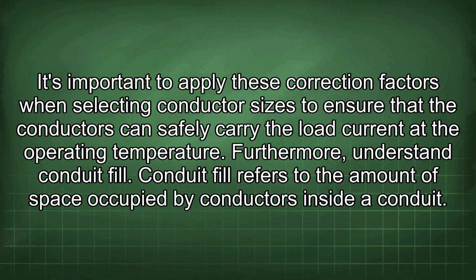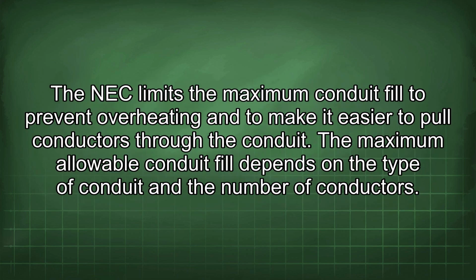It's important to apply these correction factors when selecting conductor sizes to ensure that the conductors can safely carry the load current at the operating temperature. Furthermore, understand conduit fill. Conduit fill refers to the amount of space occupied by conductors inside a conduit. The NEC limits the maximum conduit fill to prevent overheating and to make it easier to pull conductors through the conduit. The maximum allowable conduit fill depends on the type of conduit and the number of conductors.